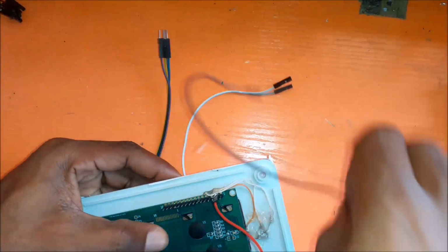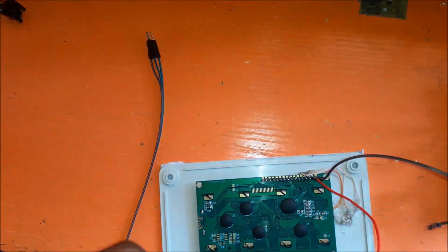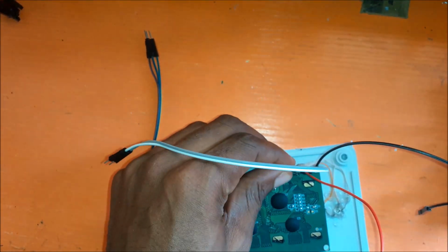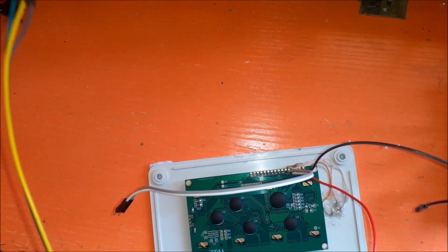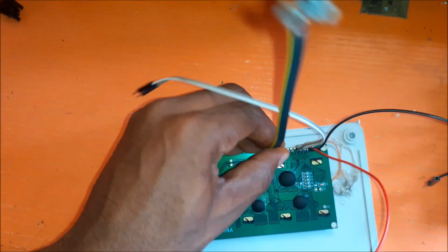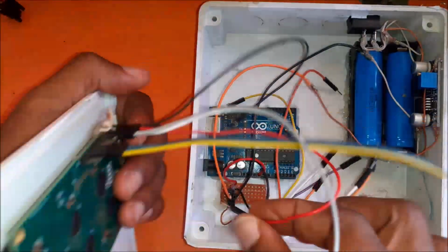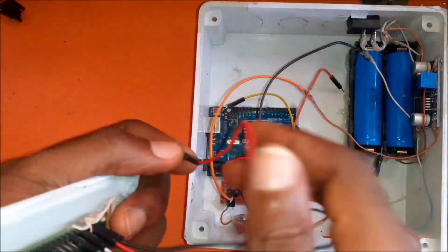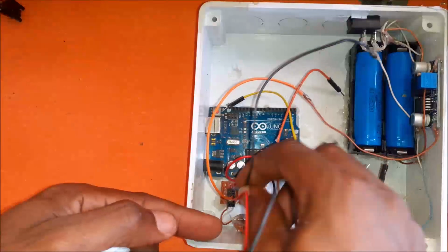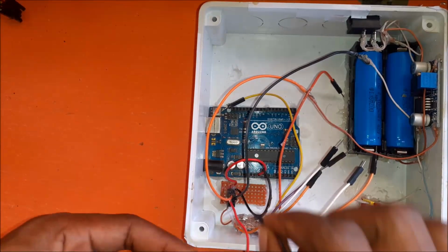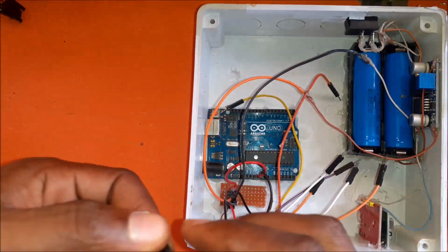Next we move to the connection of the LCD module. Since we are using a 4-bit method, we connected the LCD according to the schematic diagram. This means connecting the module to the Arduino Uno using male jumper wires. We connected the power rails first, then we connected the register select wire and the enable pin wire to the Uno board, then the 4 data wires from the Uno board to the LCD module.